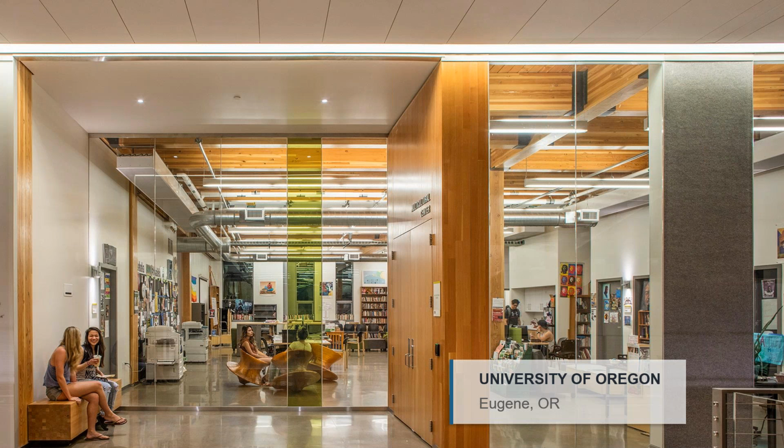Now you always need a ventilation component to it, obviously. Because we're not providing fresh air to the beams in the case of the passive unit, here we have the ceiling ductwork connected to the louver grills, just right off of that ductwork, supplying the ventilation latent airflow requirement to the space.